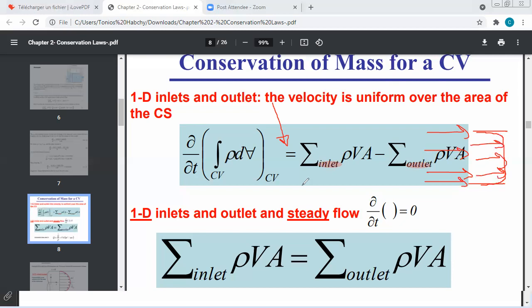However, for laminar flows, where Reynolds number is not very high, as we will see in the next example, if you have a flow in a tube, then if it's a laminar flow, we'll have a development of a parabolic profile for the velocity due to viscous effects. So due to viscous effects, you will have a gradual change in velocity within your fluid. This is the effect of viscosity.